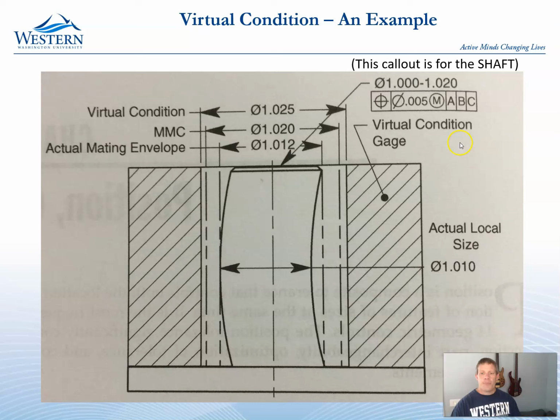And so then if we're looking at, okay, what shaft fits into that category, the shaft can have a bend in it. The diameter measured at any point has to meet the diameter tolerance, but because we have this larger zone from adding the maximum material condition and the true position tolerance, it allows us to not have a perfectly straight shaft. It will still fit into the location where we want to use it.